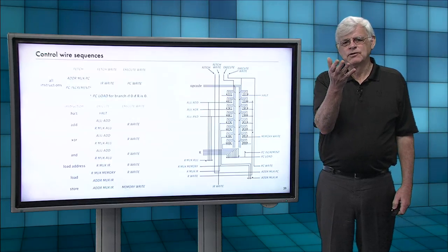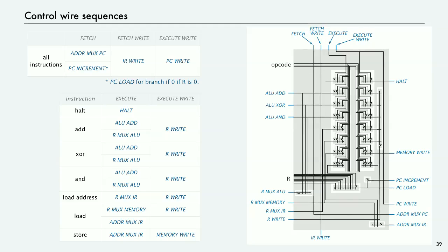And so we just make a table for all the things that we want to have happen and implement the conditions expressed in that table with a combinational circuit. The key feature of this circuit in the middle is a couple of demultiplexers that are based on the opcode. So there are 3 opcode bits, and these demultiplexers have 8 outputs, one going left and one going right.